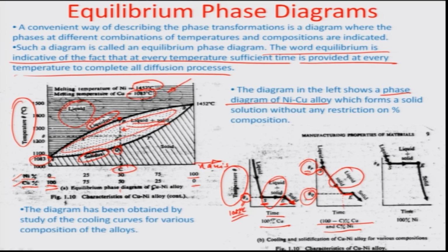So, there is going to be a latent heat phase in the solid, and then it is going to go down. So, basically what you are trying to do when the phase changes from a single phase into two phase is that you are trying to take this region and split it up into this fall in temperature versus time, where there is partial liquid, partial solid, and the latent heat part, which is separate, and this latent heat part keeps on changing as the percentage nickel changes.